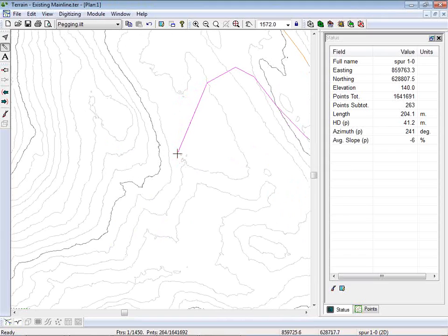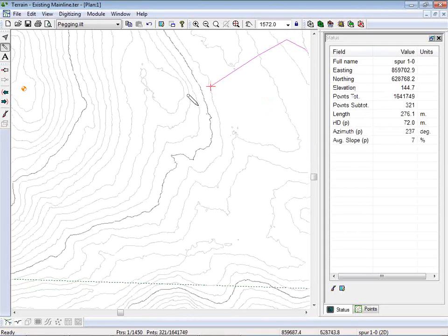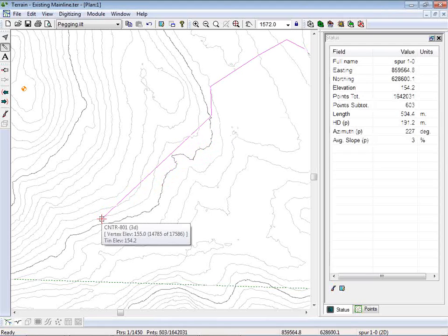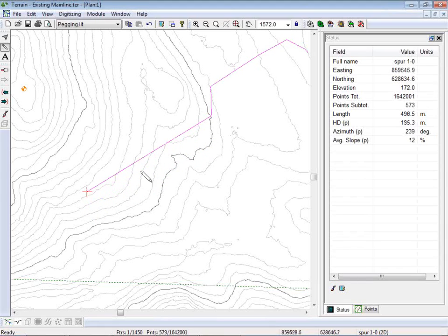Okay, back up the other side. Let's sort of go over to here. So we've got some room to start pegging, and now I'm going to start going up the hill. 27%. Let's try and keep it around 12 if possible. 13, that's reasonable. 12, okay, there we go. And then we'll go along here. Now I could just jump along like this until I get 12%, but I think you're going to need more curves in here. So I'll go back and do shorter legs.